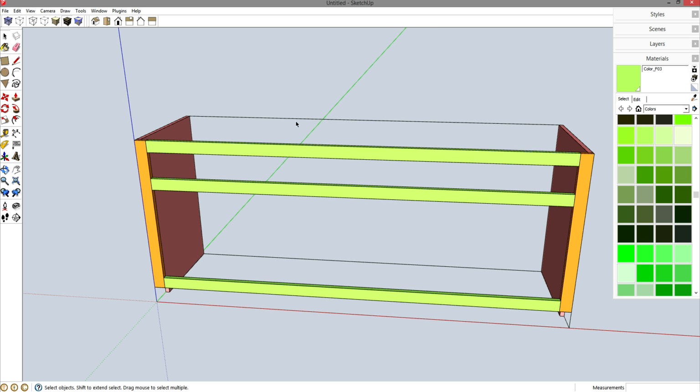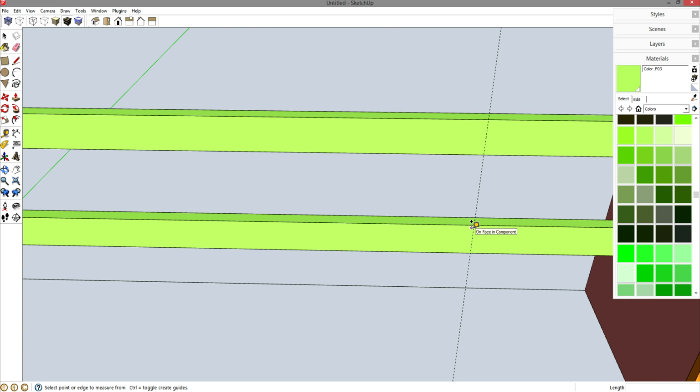Now, I don't really know how much space I need for the sink because I didn't know what kind of sink she wanted, so I'm going to make 2 fake drawers and then 2 regular drawers. T for tape measure, and let's just drop a guideline that is 17 inches away from this side right here. And I will draw a style. R for rectangle, and let's drop it off like so. First dimension is my width, and instead of going 2 inches, I need to go 2.5, enter.